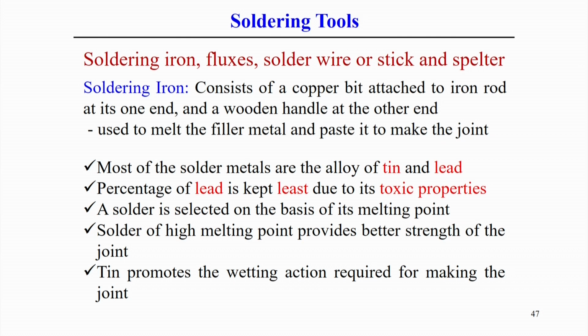This can be used to melt the filler material, and at the same time it can be used to paste that filler material to make the joint. That is the basic principle, and we have seen that the soldering process is practically applicable. Practically we can see this soldering process very frequently in the connectivity of electrical circuit boards. Most of the solder metals are alloys of tin and lead.